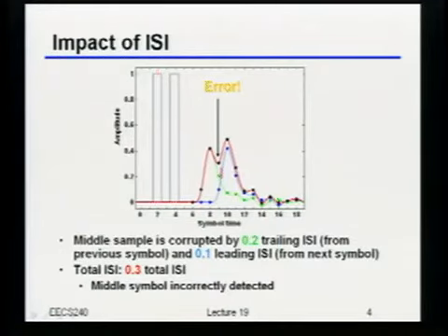So people like to categorize these into two different types of interference, and it's really just related to where in time it sits relative to when you receive the peak. All of these dots that happen afterwards, that's called post-cursor interference. In other words, it arrives after the cursor. All of the dots beforehand, that's called precursor interference. In other words, it actually arrives before your maximum signal amplitude.